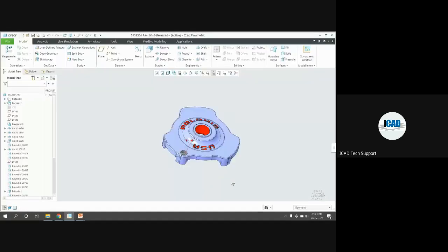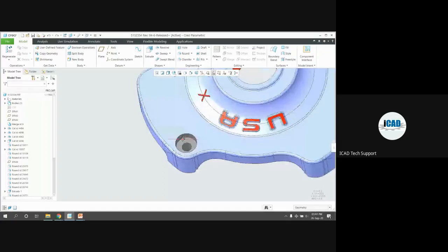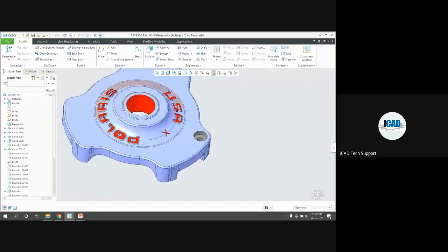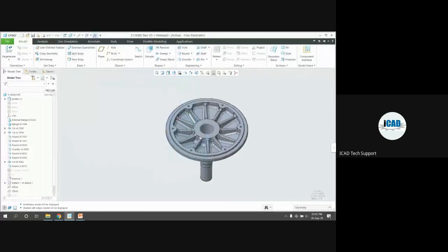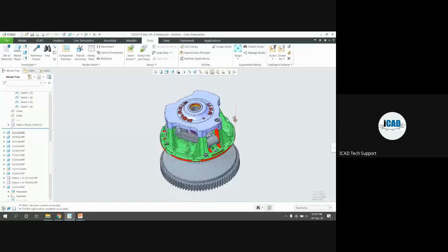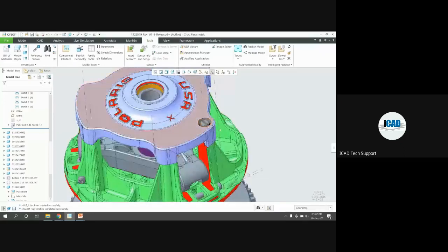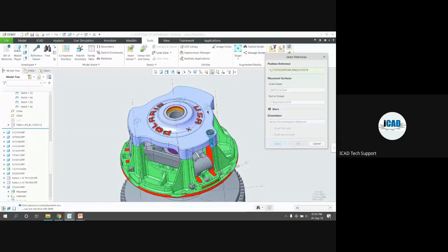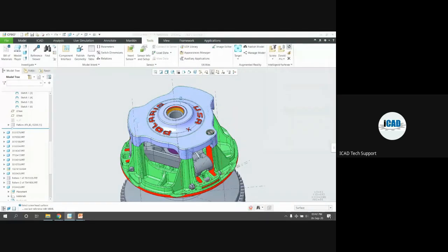I will show it here. Here you can see we have not created any hole profile for it. It will get created automatically. So if I want to use this fastener and this geometry at every point, the reuse option is available. Reassemble. So select it, select the fastener and give the other reference. Click on apply.